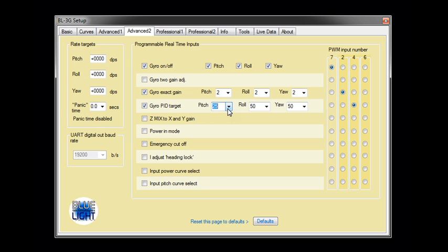This might be useful if you wanted to flick a switch and allow the aircraft to do, say, a 360-degree roll in exactly a given time. Then you could set the pitch and the yaw to be 0, and the roll rate you could set to be, say, 100 degrees per second, and then given this rather high roll rate, your aircraft can perform a roll in about 3 to 4 seconds.